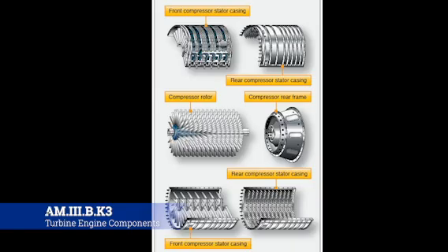Anyways, as they turn at high speed, they take air at the compressor inlet and impel it through a series of stages. From the inlet to the exit, the air flows along an axial path and is compressed with a ratio of about 1.25 to 1 per stage. So that's per stage. Every stage is getting a little bit tighter as it goes. The action of the rotor increases the compression of the air at each stage and accelerates it rearward through several stages.